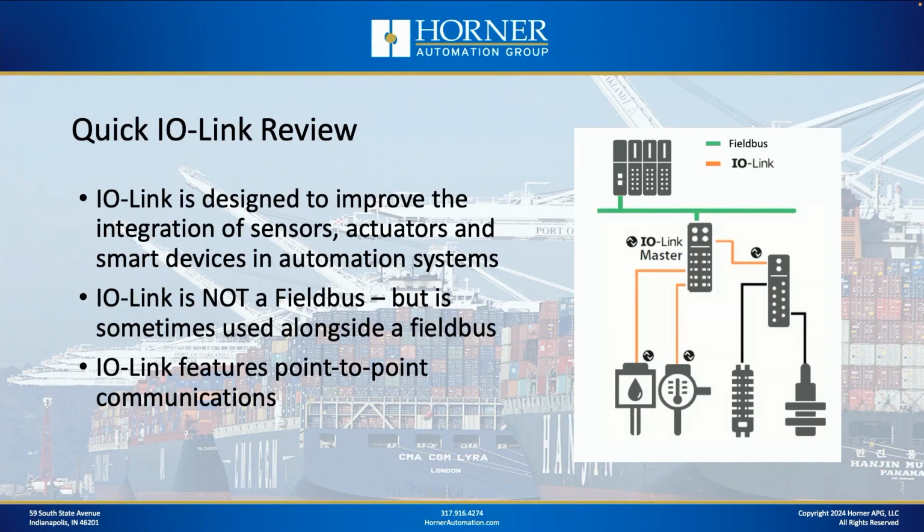Now, because we're interfacing our RFID reader over IO-Link, we need to take a quick review of the IO-Link technology. So what is IO-Link all about? Well, it is designed to improve the level of integration between PLCs and sensors, actuators, and smart devices in general and automation systems. Now, IO-Link is not a field bus, although it's often used alongside a field bus, and it features point-to-point communications as opposed to the multi-drop which so many field buses support.